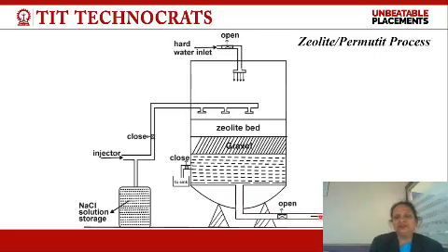You can see in this apparatus, after filtering the water with the gravel filter, we can collect it by this outlet. You should notice that at two places I have written open and open, and at two places I have written close and close. It means when we are performing the softening method, we open this passage. When water passes through the zeolite bed, it will come through the gravel and we can collect it through the outlet.